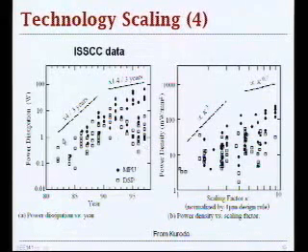What I would like to emphasize from this graph is that the power dissipation has been going up rapidly, like 4 times every 3 years. That was the trend all the way up to about the 90s, where we had two things going on: a decrease in power consumption in one direction, and also a leveling off of the power scaling trend going forward. The reason is that all the way up to the 90s, you had constant voltage scaling.